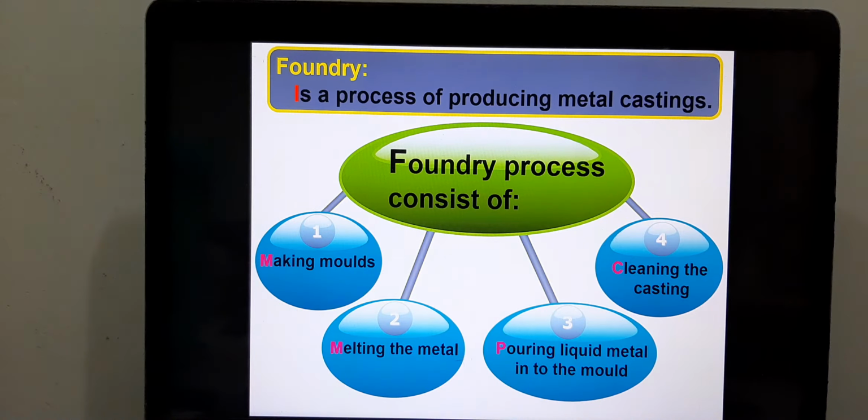Having the same concept in mind, now you're going to do casting, specifically sand casting, whereby the mold is constructed from sand, specifically silica sand. Once you construct the mold, you have your particular shape. You put in the pattern to create the shape. Then you're going to melt the metal and pour the metal to fill up that empty cavity or the empty mold and allow the metal to solidify.